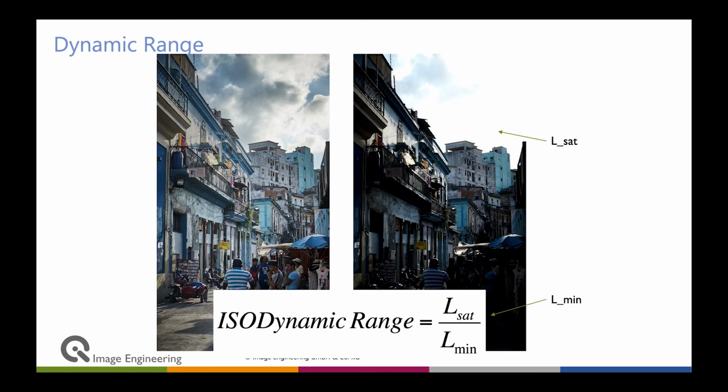That's the upper limit. Then we have the lower limit, the minimum luminance, which is defined by noise. As soon as you reach a certain signal-to-noise ratio, say less than a signal-to-noise ratio of 1, where signal and noise are equal, I have a loss of information. Less than that, there is no information. So the dynamic range is basically covering that range where you have some form of information at all. It does not really mean that is everything where you can perceive details very well or see everything. It's really about which range you have loss of information.